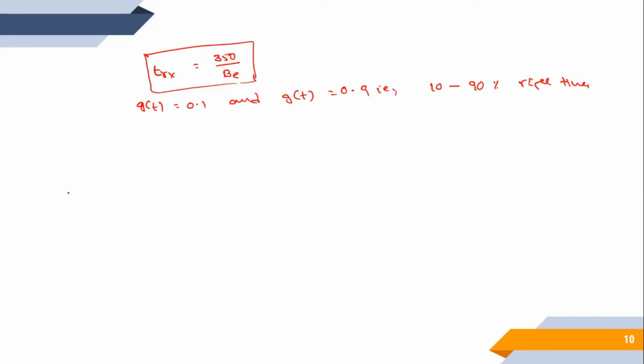Okay, and the fiber rise time due to GVD is given by TGVD = |D| L σλ. Here σλ is the half power spectral width of the source, D is the dispersion, L is the length of the fiber, and